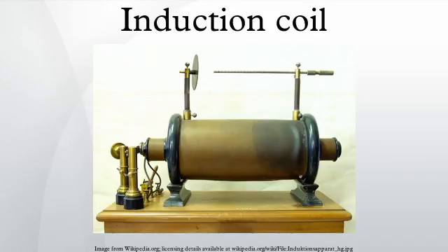The interrupter is mounted on the end of the coil next to the iron core. When the power is turned on, the magnetic field of the core created by the current flowing in the primary attracts the interrupter's iron armature attached to the springy arm, opening a pair of contacts in the primary circuit. When the magnetic field then collapses, the arm springs away, closing the contacts again and turning on the current again. The magnetic field pulls on the armature again, opening the contacts again. This cycle is repeated many times per second.